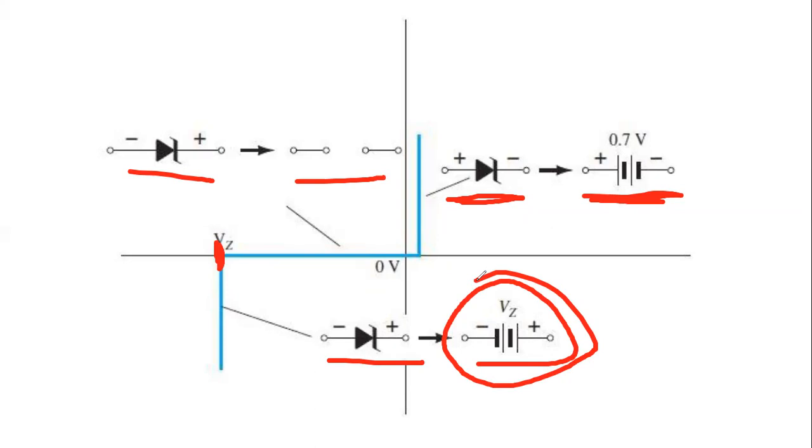So remember two things, my tips to all of you students: the Zener diode in forward bias is the same as a diode, and the Zener diode in reverse bias is the same as a diode. But when the Zener diode in reverse bias crosses the Zener voltage, at that time the Zener diode becomes a voltage source. Am I clear now? I think it's clear. Is there any question, my student? No, sir. Okay, my students, let me stop sharing.